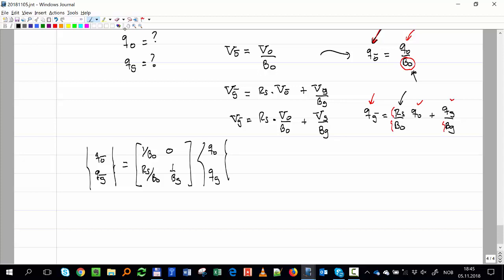Remember matrix multiplication? The contribution of Q oil comes from this times this and this times that. No contribution for the gas whatsoever. The contribution of the gas comes from this guy times this, the part that vaporized from the oil, and this guy times this, which is just the expansion of the gas. And this matrix is a function of pressure and temperature, a function of pressure.